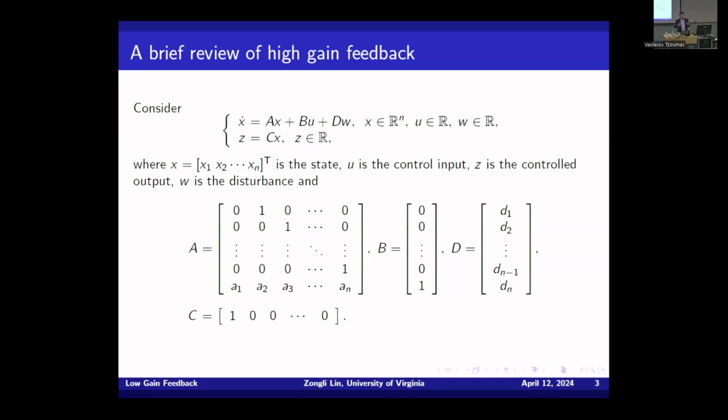So basically, all I really need is not zero. I just need the system to be minimum phase. But if I assume there's no zero, it's always minimum phase. Is that right? So this is just for illustration. So the special form of C here shows that this single input, single output system does not have any zero.